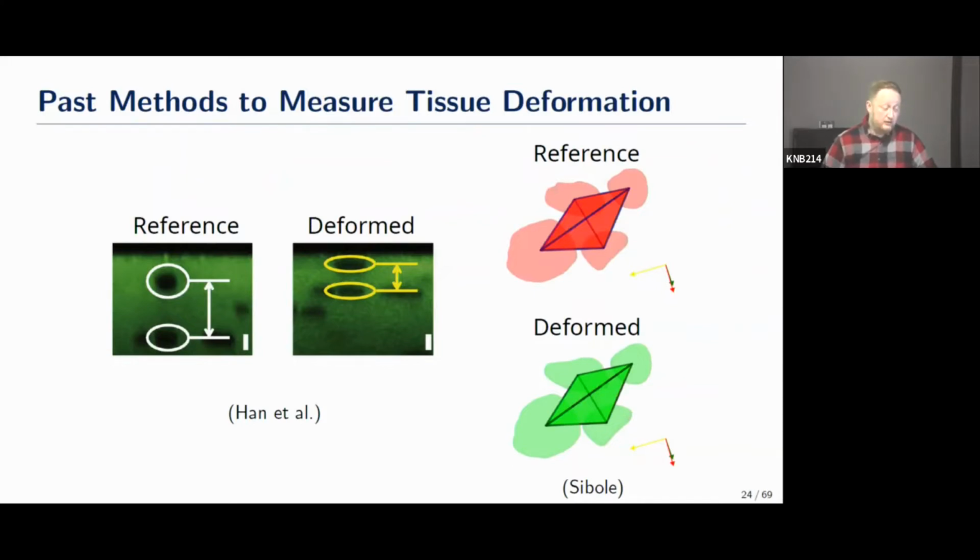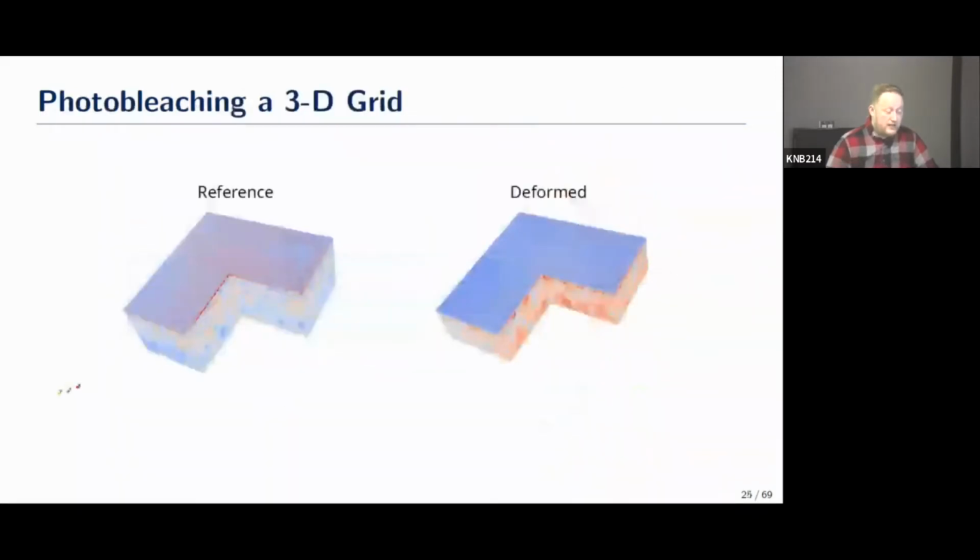In my master's work, I extended this. If you consider the centroids of 4 cells, you can build a shape called a tetrahedron. And then from that tetrahedron, you can calculate the deformation gradient again, as I said. That's the minimum sort of shape that you need to calculate that if you compare the shape of tetrahedrons formed in reference and deformed configurations. The problem with that approach is that in cartilage, the distribution of the cells is quite sparse.